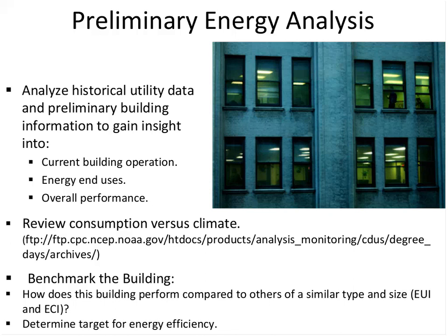And we're going to benchmark the building. We're going to determine how this building operates compared to similar buildings in the same climate zone. Same type, same size, and we're going to determine a target for energy efficiency from that. You're going to look at how well your building performs and get an idea of how much improvement may be available within that building.